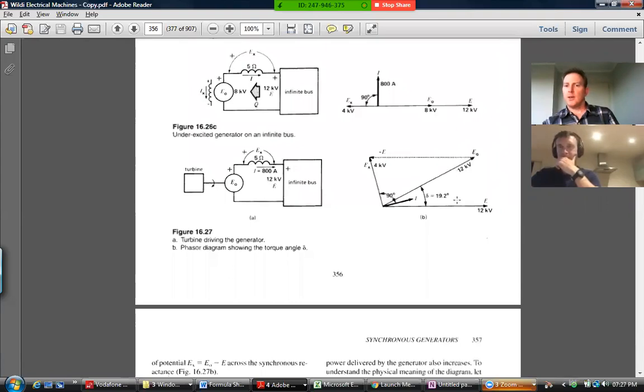But because it's ahead of the other one, there is actually a potential difference, and current will actually flow, which we know anyway from a three-phase system. Yep. All the voltage phases are the same size, but because they're out of phase, you put a resistor between one line and the other, and some current will actually want to go through there because they're not in sync. So that difference over there, if you subtract again that number or that phasor from that phasor, the difference that you get there would be this EX.